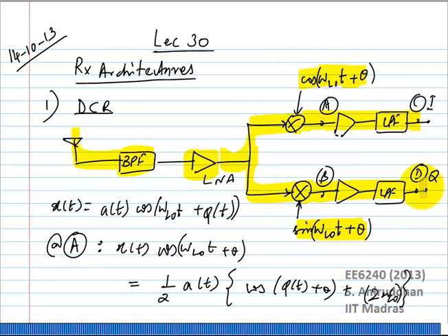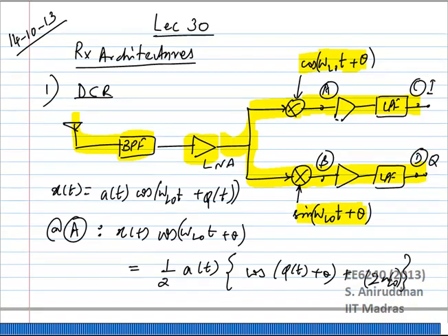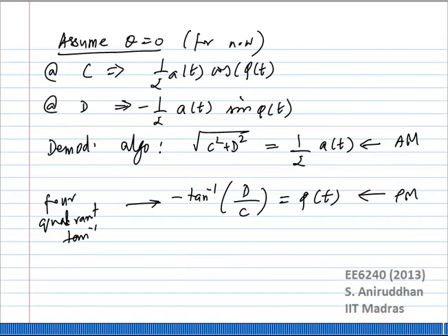Okay? And as far as the architecture goes, pretty straightforward, right? You only need two components really. You need an LNA and you need the single sideband mixer. That is, you need the IQ mixer to actually separate out the I and Q channels. Apart from that, everything else can be done on a case-by-case basis. And it is very easy, now that the two channels are separated out, you can either extract the amplitude, the phase, the I and Q components, whatever you want.